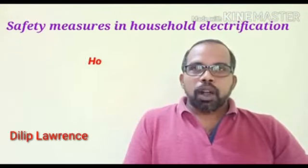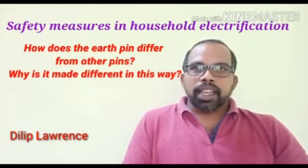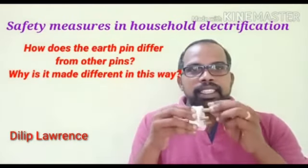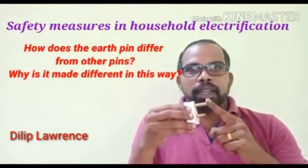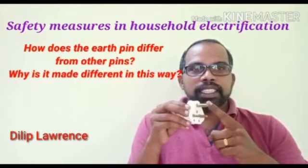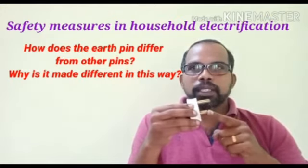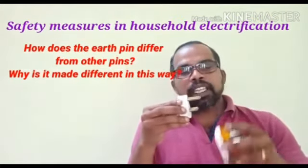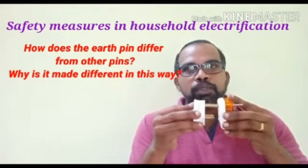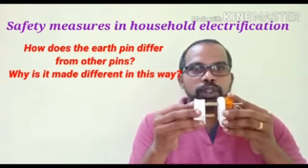Let's see how the earth pin differs from the other pins. Why is it made different in this way? The length and thickness of the earth pin is more than that of the other two pins. Since the length is more, when the 3-pin plug is introduced into the socket, the earth pin comes into contact with the circuit first.